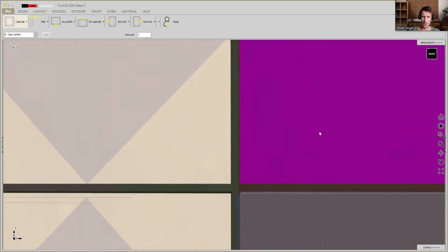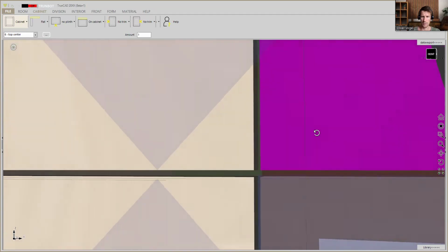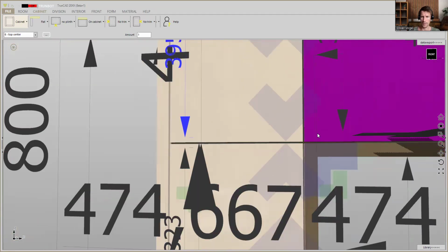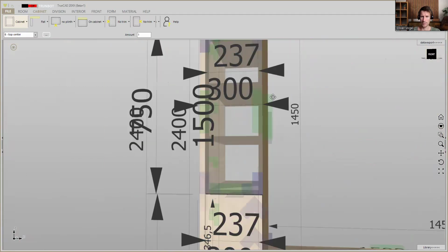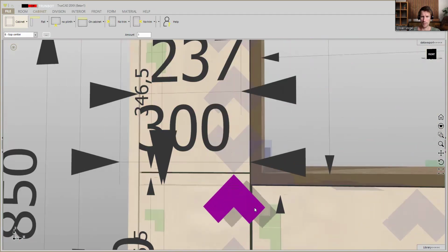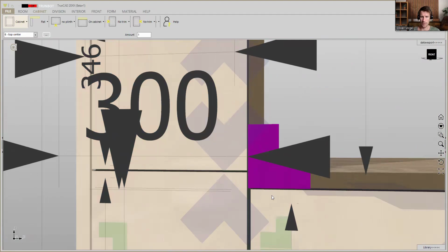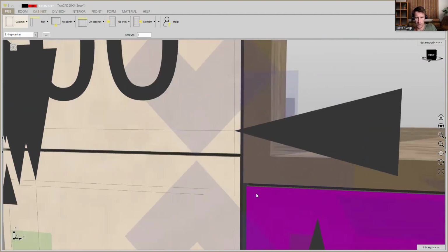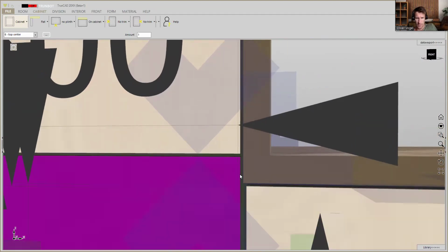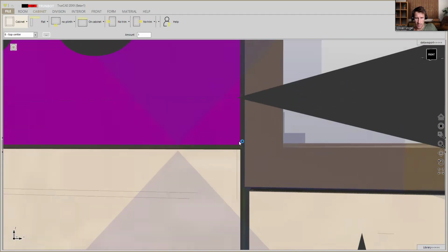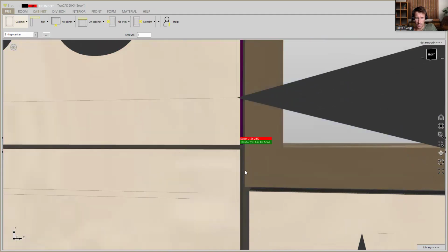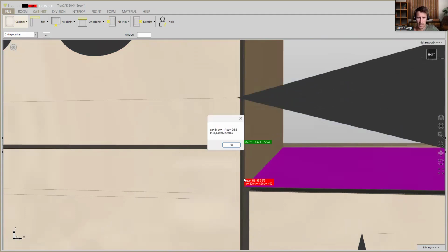So like you see now, everything looks perfect. So we're doing the same on the bottom left. We measure here the distance. Click on here, keep the control button pressed, click on here until it's turned green. And here again we see we have a difference dz of 26.5.